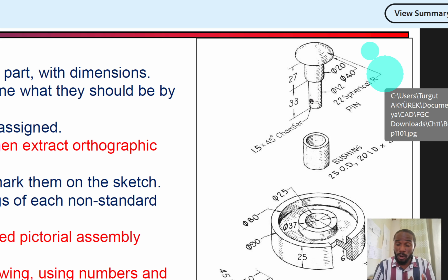Then there is Revolve, and then there is Sweep, there is Loft, there's Coil, right, and a few others that take a 2D profile, and then depending on its action, it creates a volume, either by sweeping that through a distance or sweeping it along a path or revolving it about an axis and all of that to create a volume out of it, a three-dimensional object.